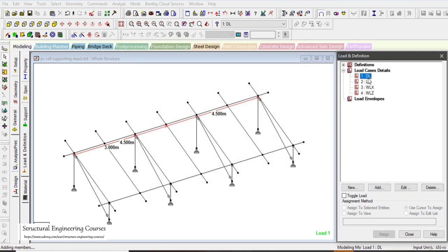So I am not applying the seismic loads because they might not matter in this small steel structure, but I had already taught you how we can apply this earthquake loading for the Indian standards. So that is why I am not repeating the arrangement here. My approach is to teach you how we can correctly model this type of steel structure arrangement, how we can apply wind loadings, and how we can analyze and design a cold form steel structure as per the Indian standards.